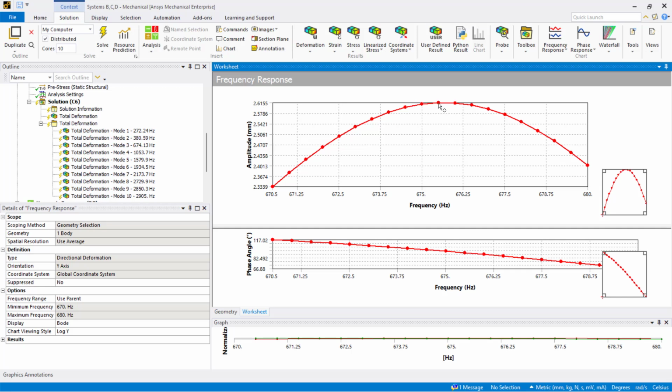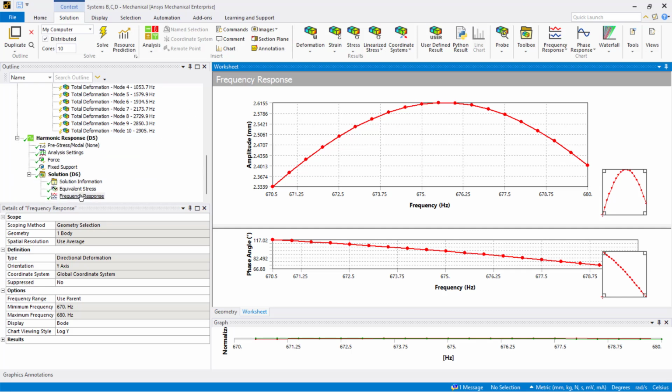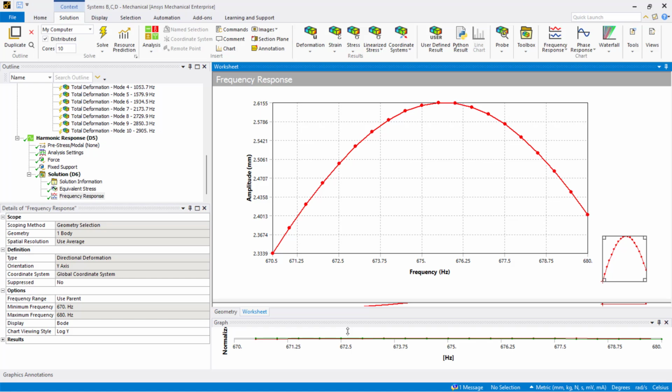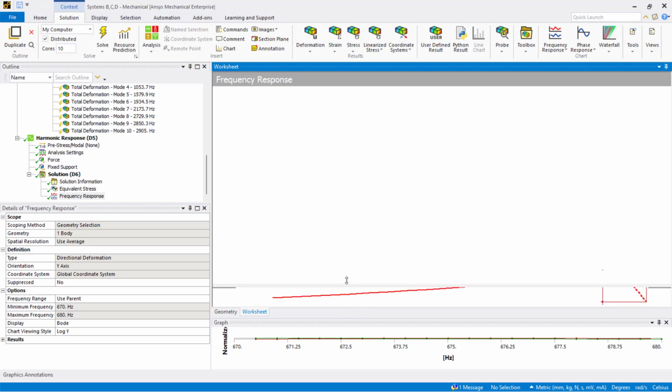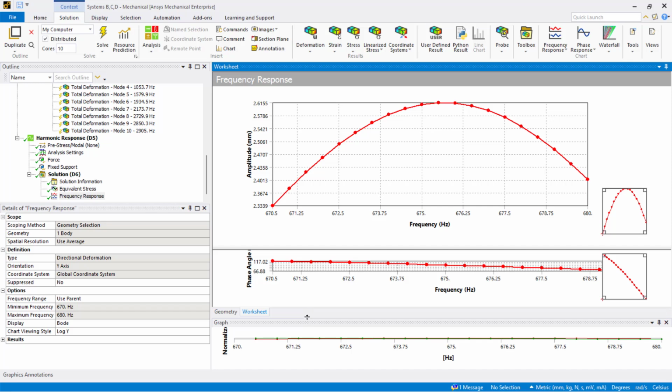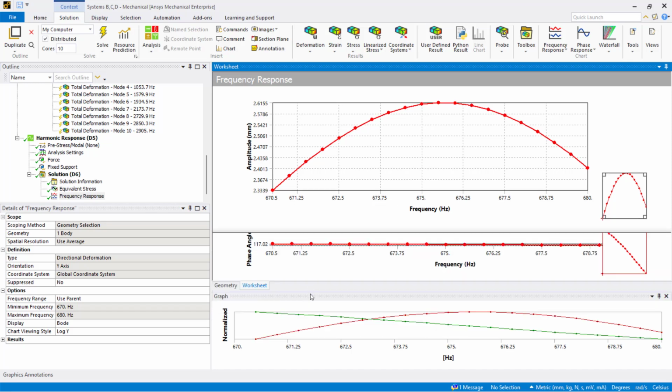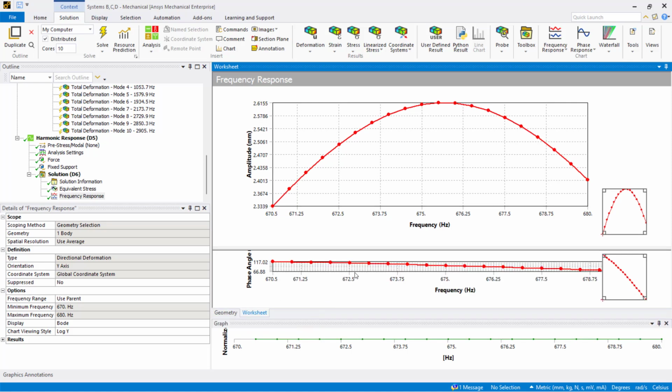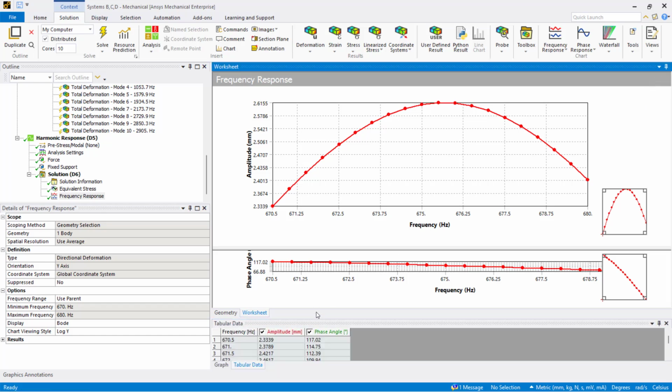How do I check the exact point here, which is this point? How do you check it? Just the table, the down table, or yeah, I'll drag that down, the table with the maximum displacement based on that. Sorry, not here. Those results will be there. Can you drag it up? No, the table is not here. So for that, I should go here. Tabular data I should activate.